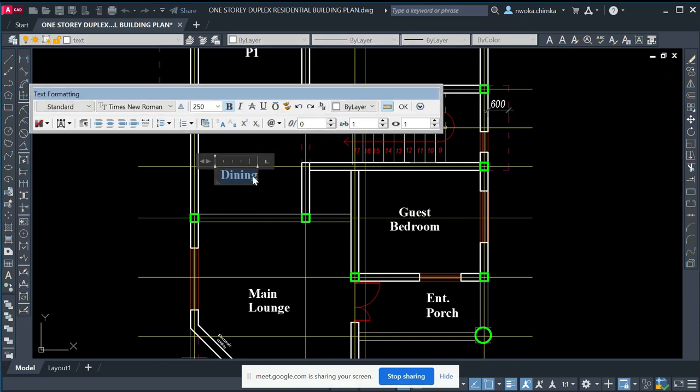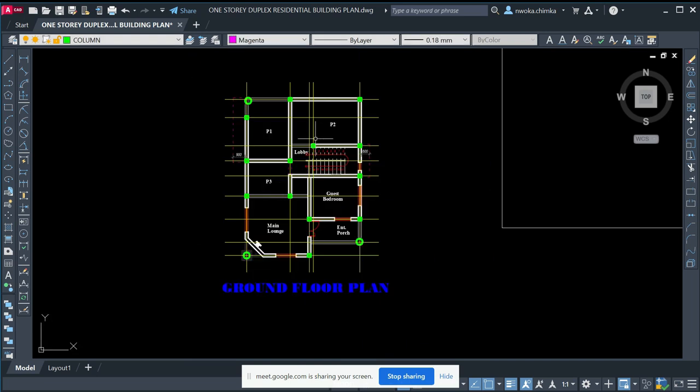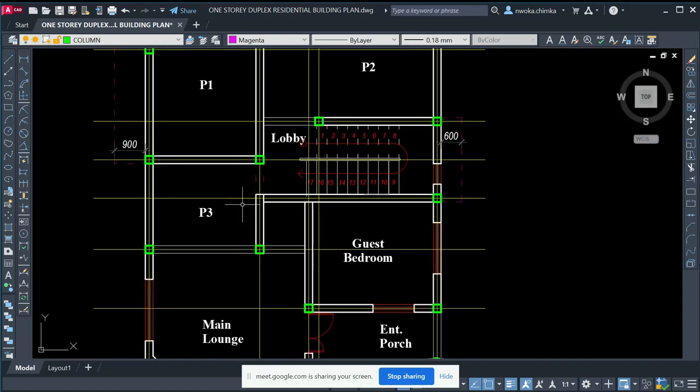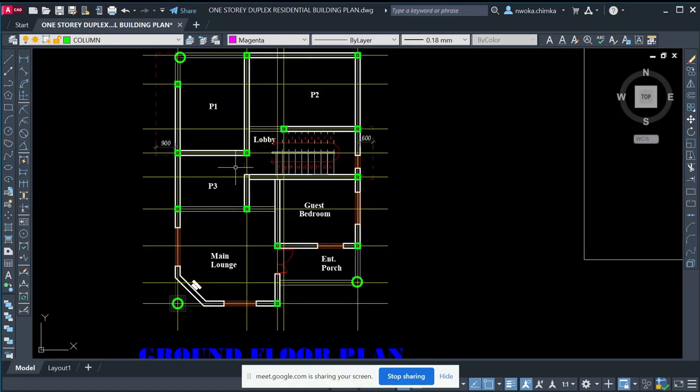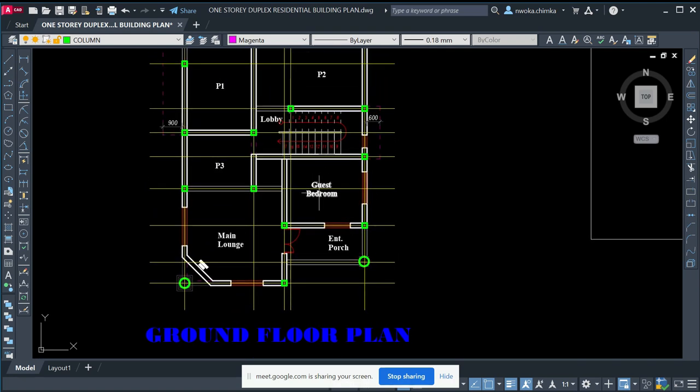Which means you'd have to divide the panel, split the panel probably into two, which means you'd have to introduce a beam and columns if necessary. When it's more than 30 square area, you have to do what they call internal beams on that area to be able to break that panel into two, which are crossing. Exactly, that's fine.